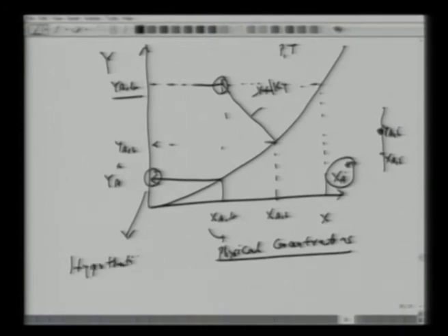So why hypothetical? Because YA star, we are saying that it's in equilibrium with XAB. In other words, if we have a system where interface concentration is XAB, then concentration in the gas phase would be YA star. But we don't have that. We have interfacial concentration at XAI and YAI. So it's hypothetical YA star, as if we have XAB in equilibrium with Y star.